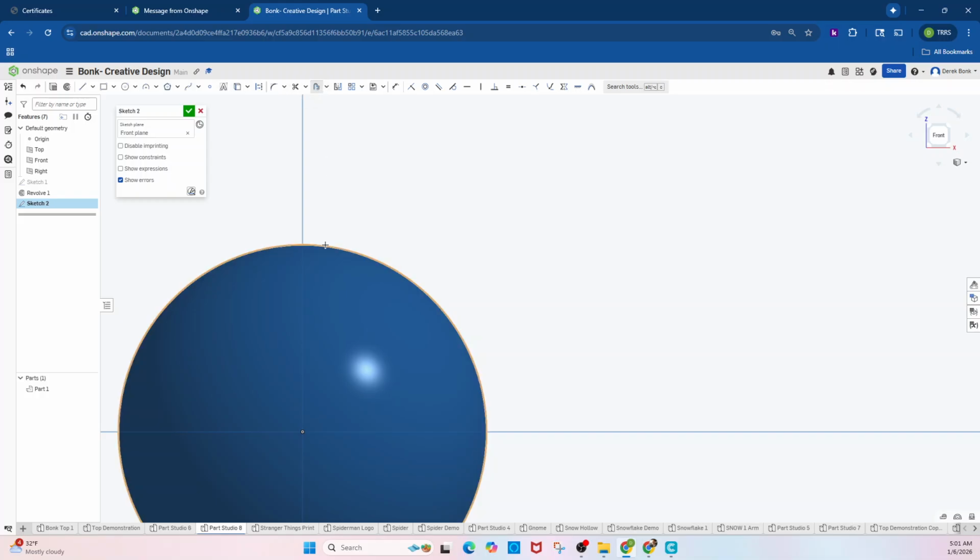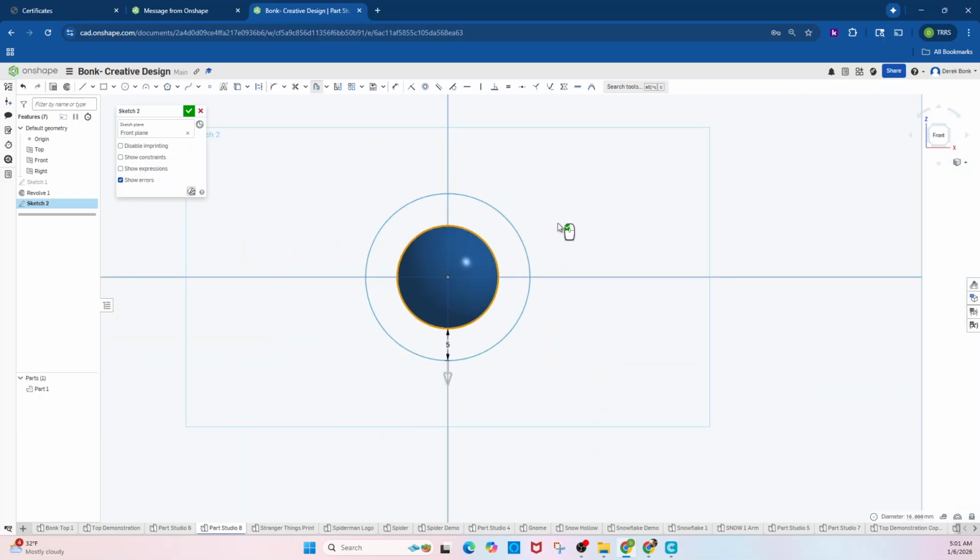Click offset and then click that line, and it's going to push a line, and we need tolerance. If you grab this, you can drag it. We need a very, very tiny gap in between the 3D printed top and the marble. If you don't put a space in there, if you make it exactly the same size, you won't fit the marble into the top.